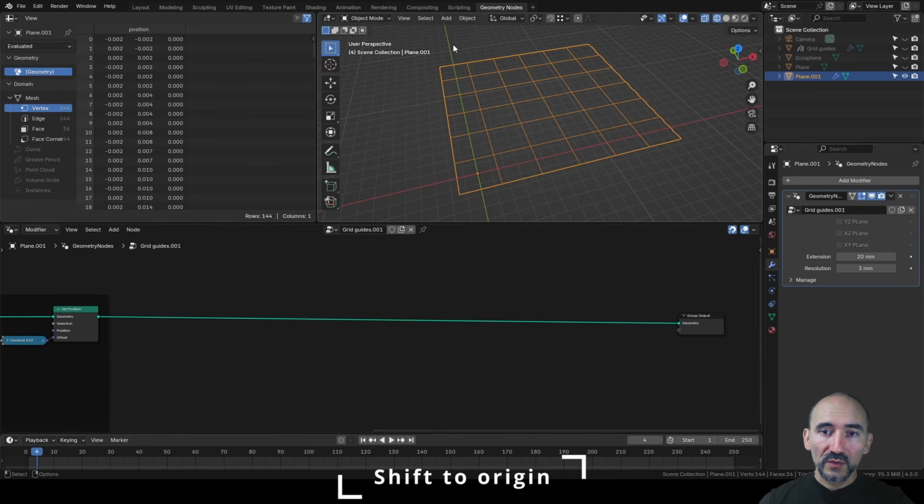Okay, so what we can do is to take the entire object, calculate the bounding box, and shift by this distance, so the half of the entire size in x, the same in the y-axis, and subtract the resolution of the single square divided by 2. Because we don't need to move by this part, because the object is already shifted by this half size in the x-axis with this little negative value, and on the negative y-axis by this little negative value.